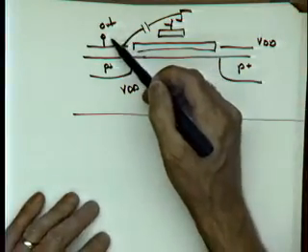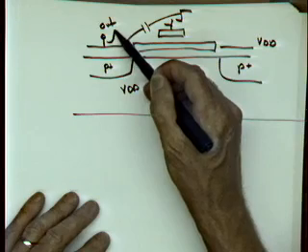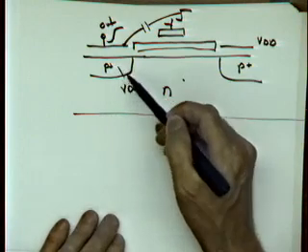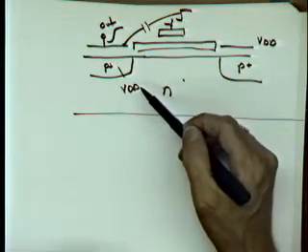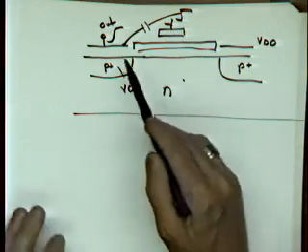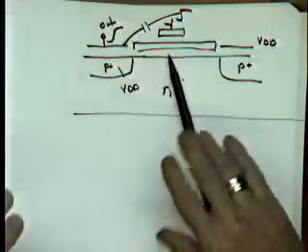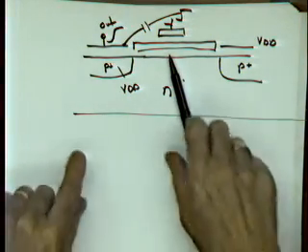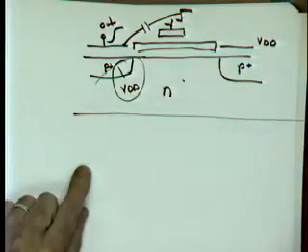Now, what's happening if I now start raising this output voltage above VDD? This diode is here, right? There's this diode which typically is reverse biased. It's definitely not on. But if this voltage here, V out, is going more than one diode voltage, 0.6 volts above the rail, this diode turns on.